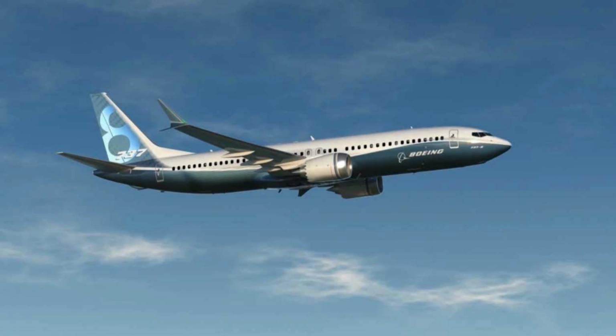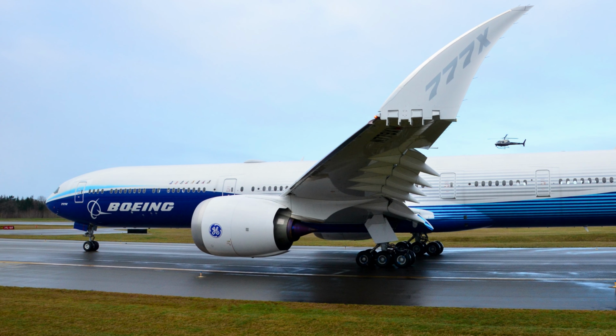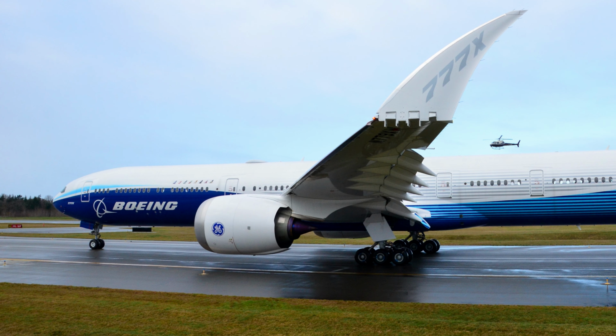Unfortunately, their effectiveness at reducing wake turbulence is very limited during the times when it's needed the most. The wake turbulence is largest when the aircraft is flying slowly, and winglets are least effective at low speeds. The case against tapered wingtips is that it greatly increases the aircraft's wingspan. That makes it harder for the aircraft to fit into hangars and airport gates. A solution to this problem is brought by Boeing in the 777X aircraft, which is fitted with foldable tapered wingtips.